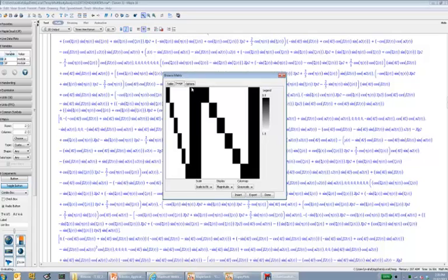The only set of values that they all share, the coupling terms, are the terms that are associated with the position of the platform and the orientation of the platform. Because at this point we are assuming that is known, these equations do not need to be solved at the same time, which is a huge advantage that we just found out. Of course we knew that, but we just found out that instead of tackling the big problem of solving this constraint equation at the same time, we can only look at one leg at a time.